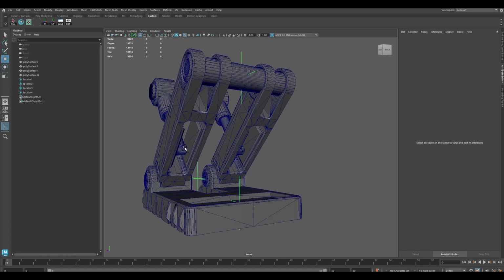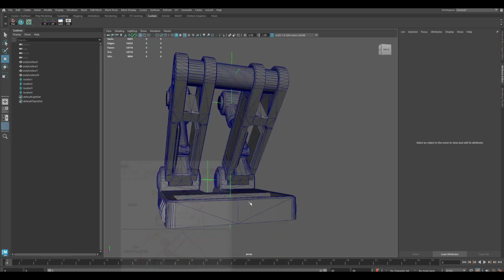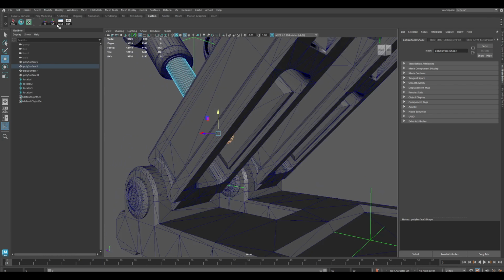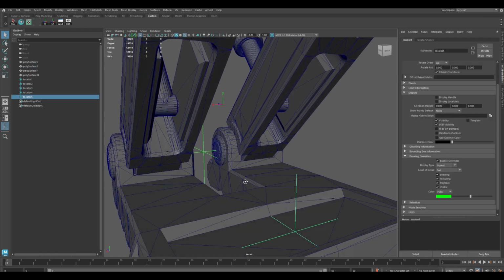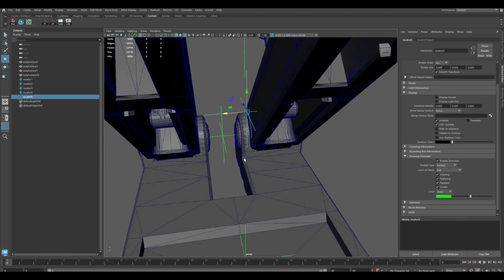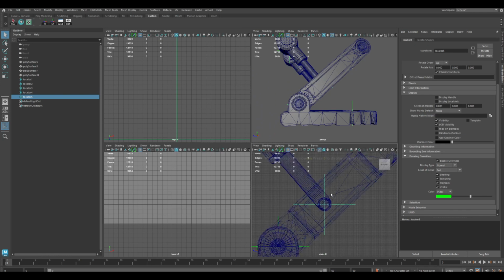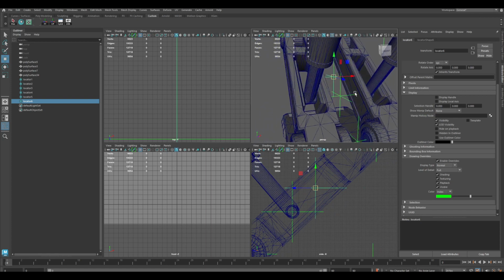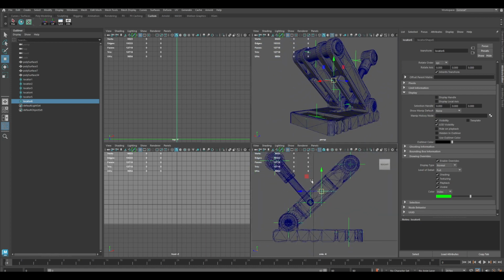And for the last two, I'll need the two places that they connect in the middle. As you can see, this one and this one. For the first one, I have it here. Let's show the rotation axis. Duplicate this locator, snap it here. Snap again to the middle. And the last one will be duplicated and will be here, the top part of this plate here that is holding the two suspension arms. These are all our locators done.